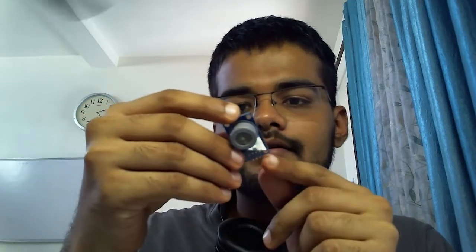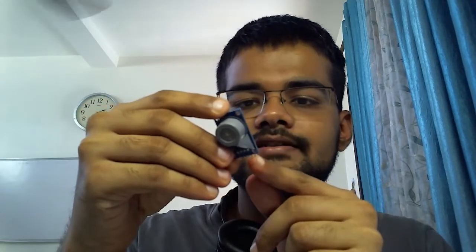My name is Pracheth, and in this video, I'm going to show you how to make a CO level sensor or air pollution level meter using RPI Pico and this sensor MQ7. So this is a sensor MQ7 which is sensitive to the CO gas. It has got 4 pins which are A0, which is analog output, D0, ground, and VCC. So we are going to use ground, VCC, and A0.